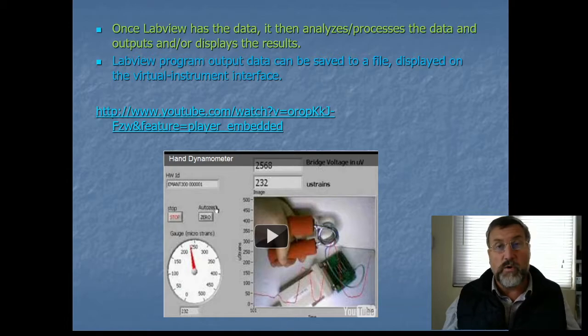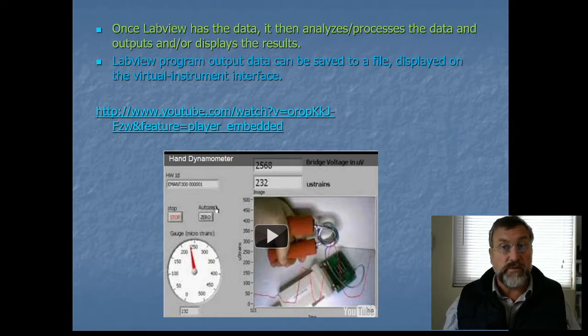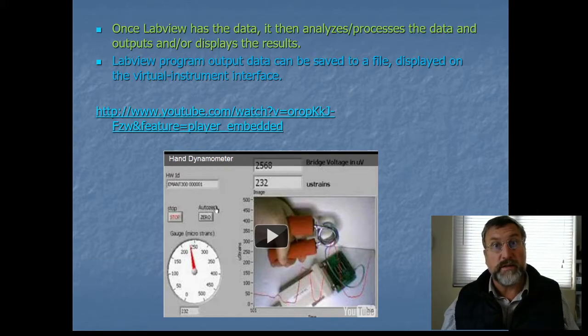For example, was it a forming defect for the tile, or was it a print problem? And then to address the relevant part of the production process. At the moment, you probably do that manually, but ideally, the long-term solution would be to be able to recognize the kind of error you've got and work out automatically what corrections are needed to give you the right kind of product you're looking for. So that's called adaptive control.